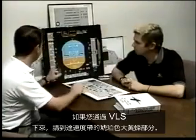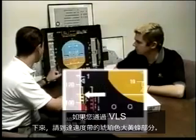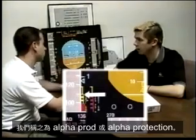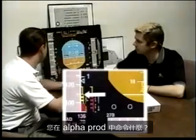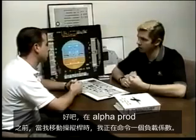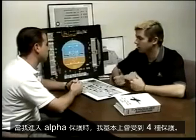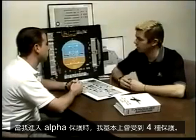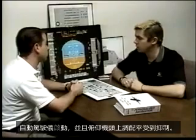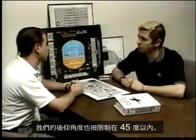If you come down through VLS, we get to the amber bumblebee portion of the speed tape. Describe to me the top of that. We call that alpha prot, or alpha protection. And what are you commanding in alpha prot? Well, prior to alpha prot, when I move the stick, I'm commanding a load factor. When I get into alpha protection, I've got basically 4 protections that go on. We use the acronym ASAP, which is AOA is commanded, the speed brakes retract, the autopilot kicks off, and the pitch nose up trim is inhibited.